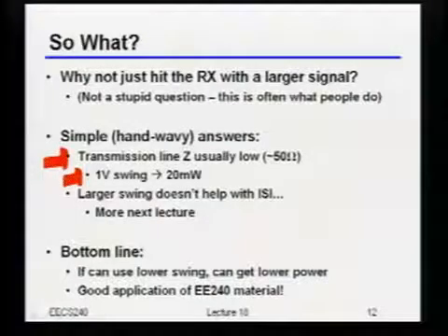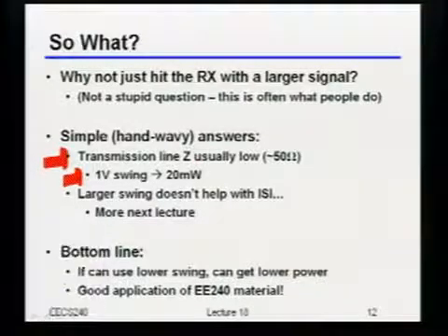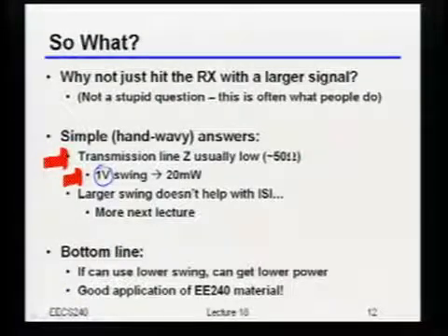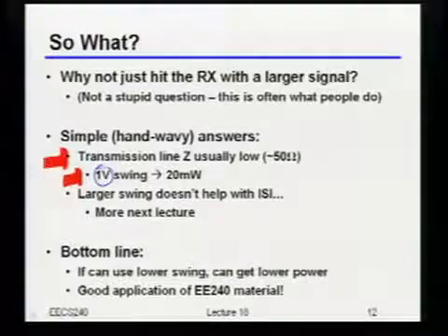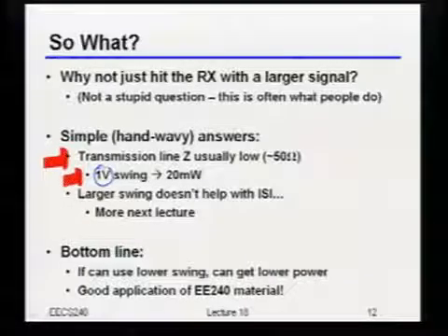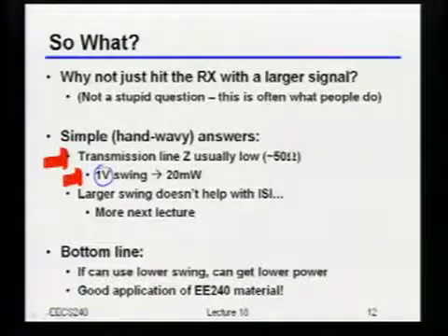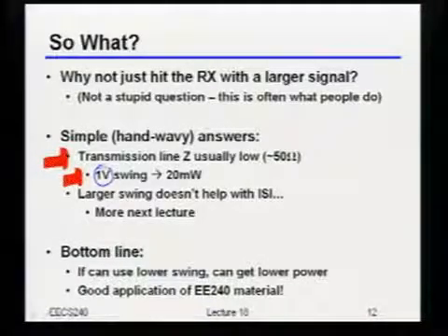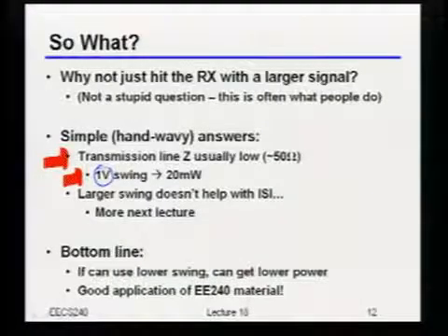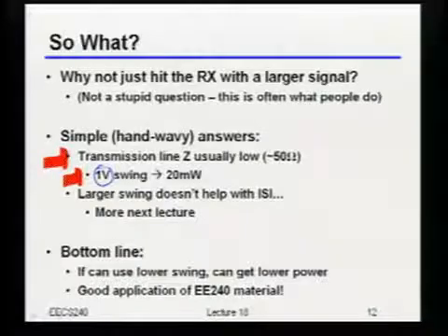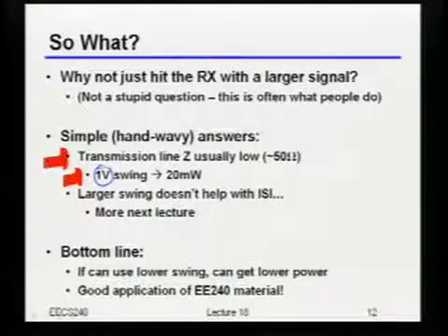Because in fact, if you think about it, on the receiver, if I wanted to generate that same 1 volt of swing, I claim I can do that probably with a lot lower power. And maybe in fact I don't even need that much swing. But even if I wanted it, I can probably do it with much lower power. Why do I say that actually on the receiver I think I can generate larger swings with lower power? Any thoughts? You're now using on-chip wire.